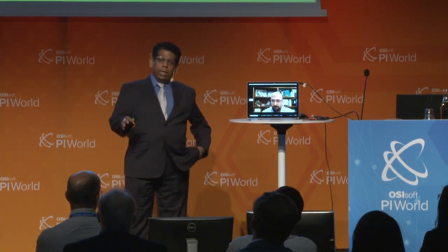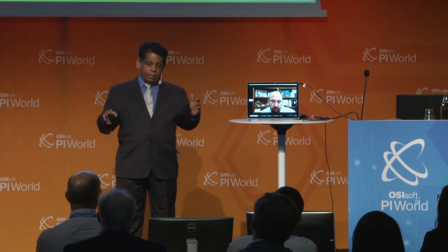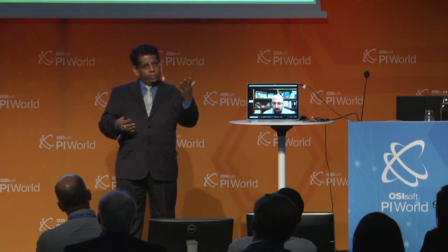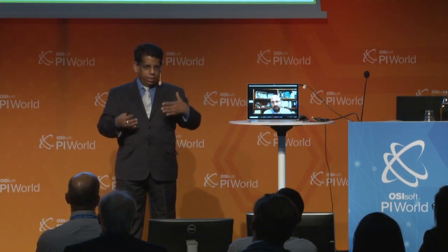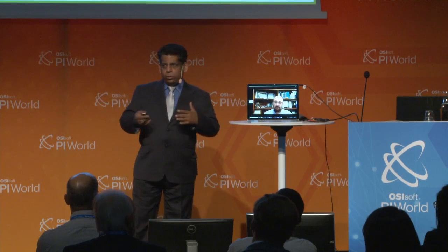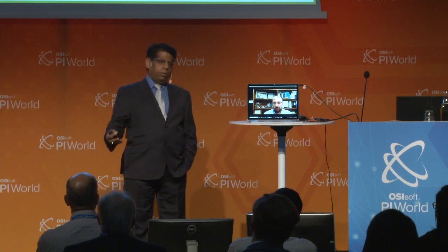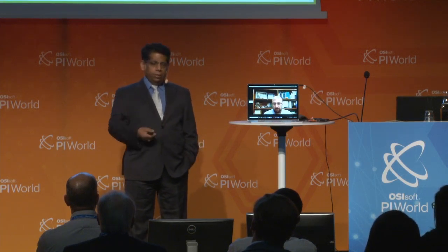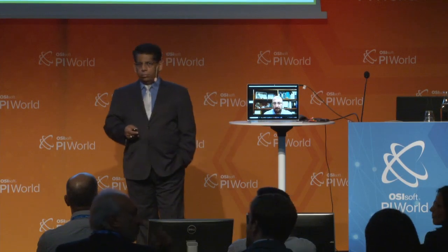I just want to add one thing. The reason we also like the Pi system is because a lot of people have looked at Pi as the historian and real-time data. But there's a whole new thing, called future data, and that's what we do. When we do the 5-minute, 15-minute and 30-minute predictions, we're sending them back to their Pi server. So when the operator opens up their Pi Vision screen, they're seeing not only their current data and past data, but also the prediction on the same screen. Those are the benefits we're getting out of Pi. And then they can do further analysis of that data or whatever recommendations we're giving using different tools. Thank you.